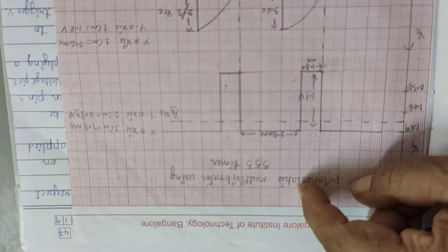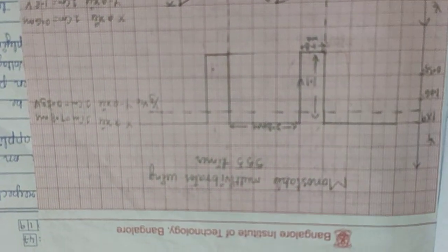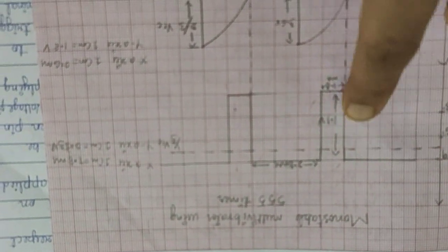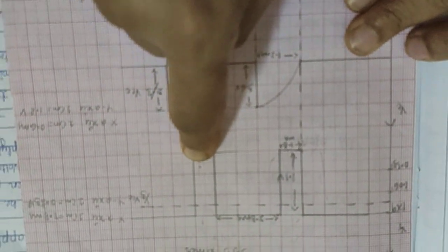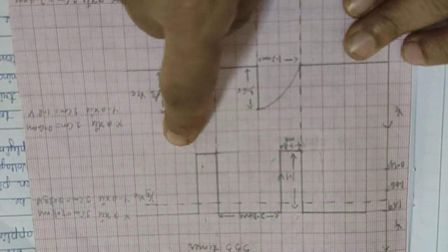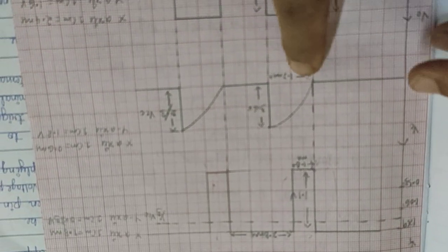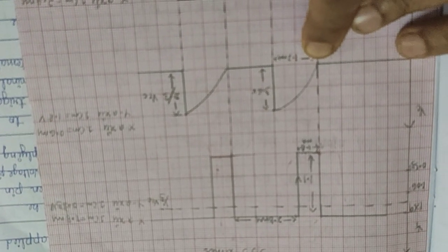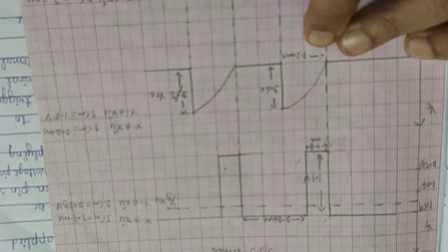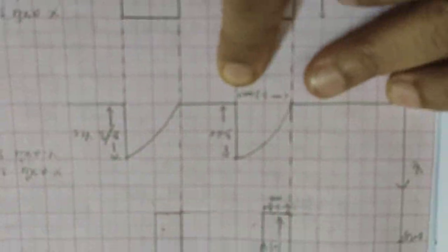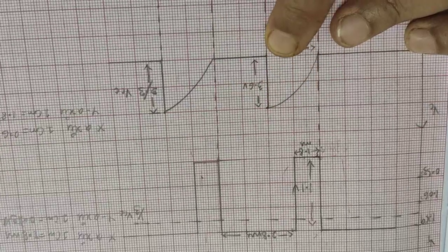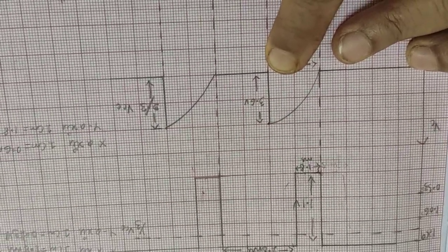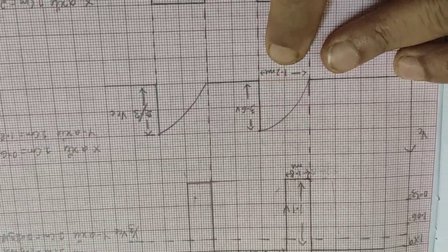Output taken is as follows. This is the monostable 555 timer. This is the voltage that was given for the timer in the trigger pulse. This is the voltage across the capacitor. You can see 1.2 milliseconds. It is getting charged to a maximum of 3.6 volts, which is equal to 2/3 VCC.